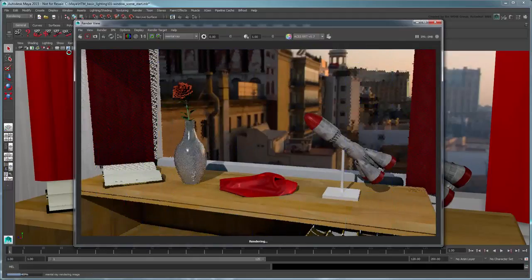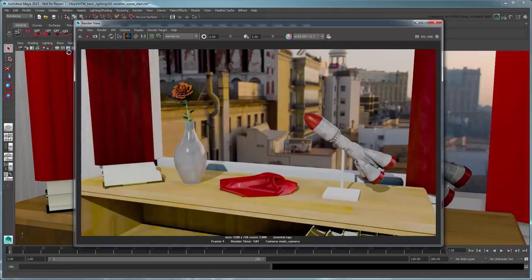As Maya renders the scene, things seem fine, but once finished, the resulting colors suddenly get completely overblown. So what happened? We basically told Maya to include an output transform to all our colors, on top of what we're seeing in the workspace, to make the render appropriate for viewing. However, the image in our render view is already being transformed by the view transform.